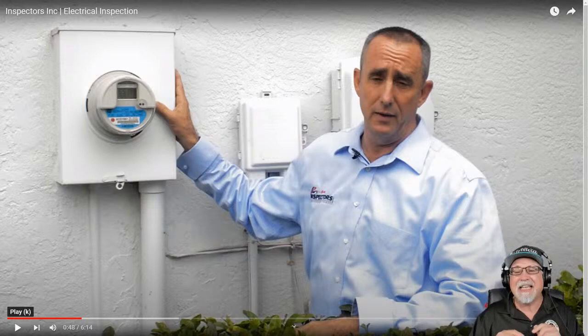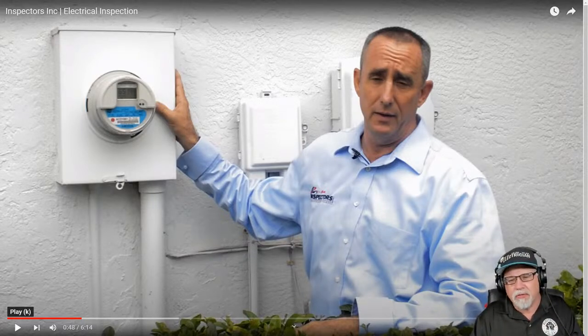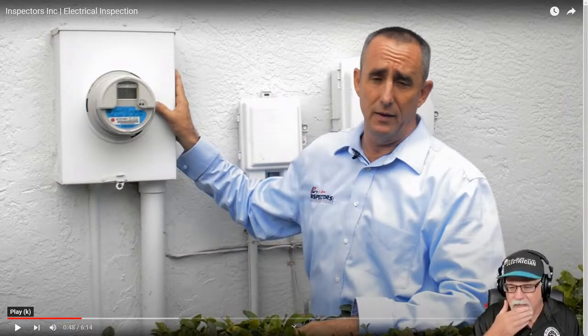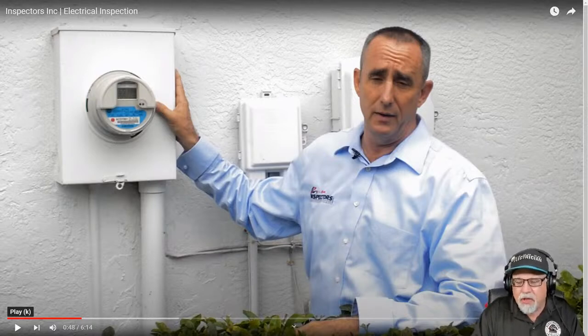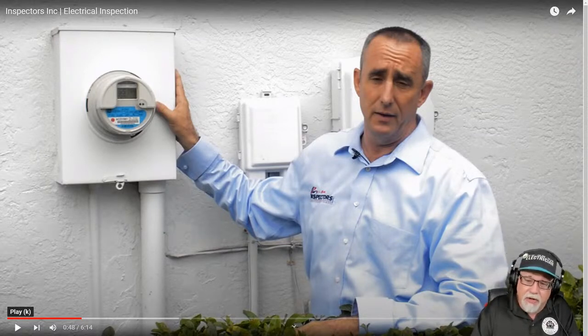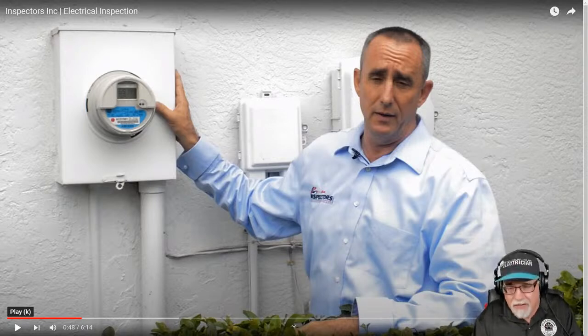Also, he said rod, not plural. In the National Electrical Code, and of course we're going to use the 2020 for this, because it could be older, but I'm just going to use the 2020. You have to have 2 ground rods unless you can prove that one of them meets 25 ohms or less. And you can't do that with a regular megger. You're going to have to use a ground resistance meter or a 3-point fall of potential meter in order to determine that. Most electricians aren't going to do that. So they're going to put what? 2 ground rods in.